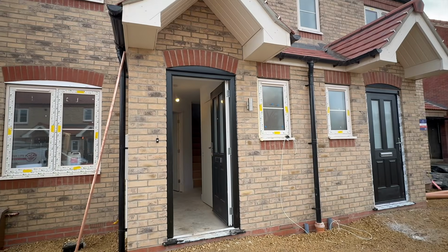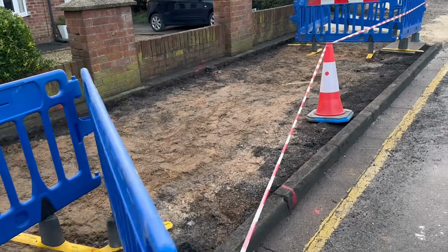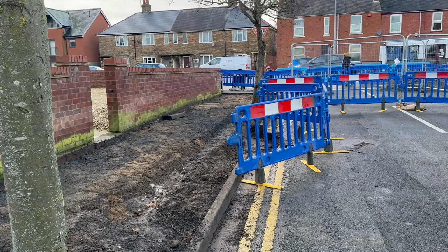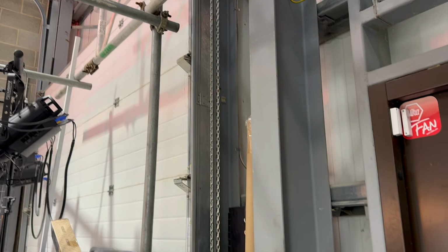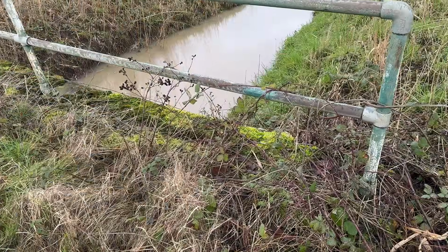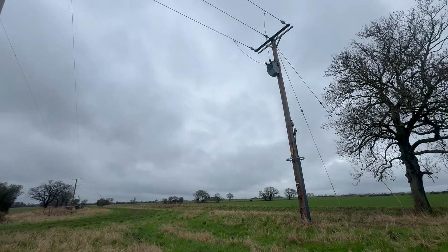On real sites, these parallel paths are common. Buried metal water pipes are one of the biggest contributors, especially older pipework that can run long distances and effectively export your test current well away from the electrode under test. Gas pipes, structural steel, cable sheaths, reinforcement in concrete, ground-mounted metal fences, and even nearby pylons can all provide unintended return paths. When your test current finds one of these routes, it will use it.